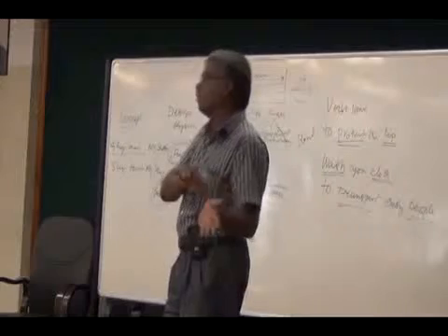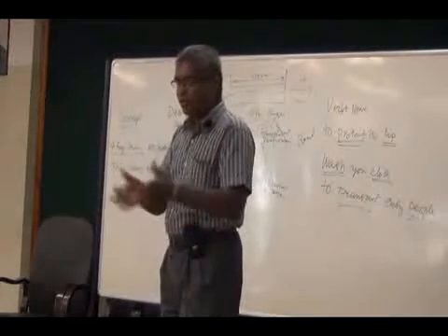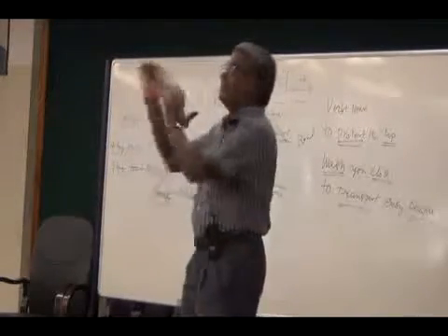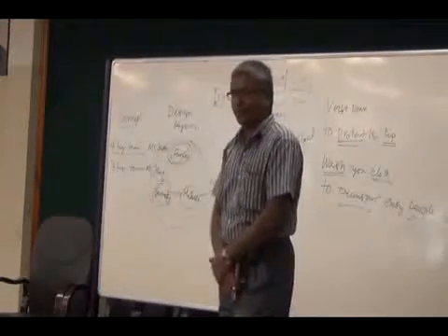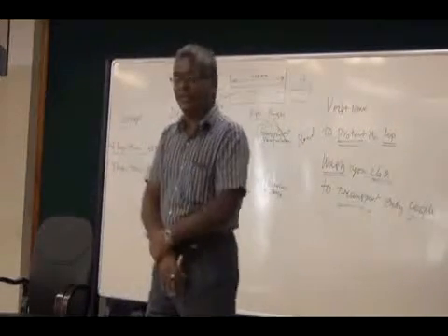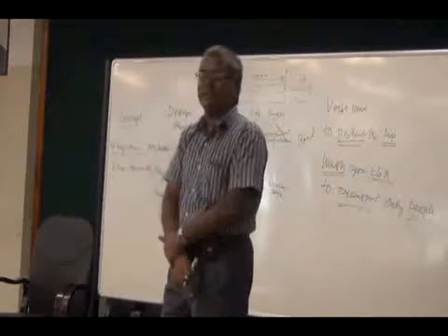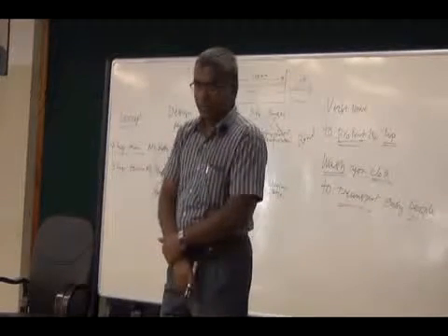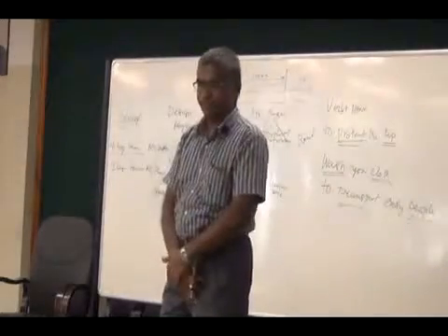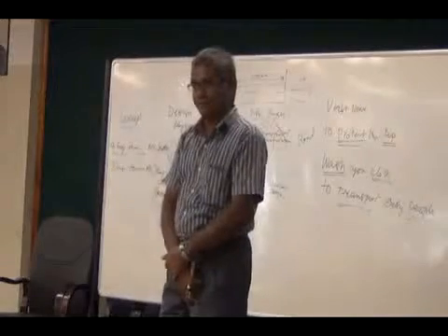Obviously, when you choose the geometry, you are also sizing up the material. And once you have chosen the material, the manufacturing process is limited, because for a material there is a set of manufacturing processes. And for that manufacturing process, the grain structure you are likely to get is only a list, that's all. You cannot get anything beyond that. And for this grain structure, material properties are fixed. And for these material properties, this is the performance you will get.